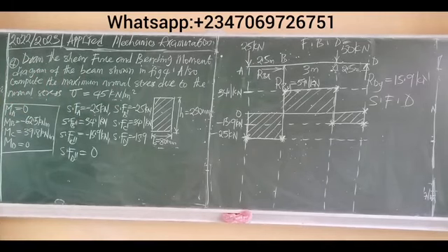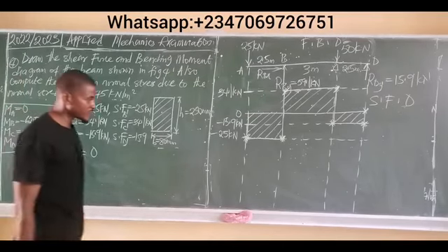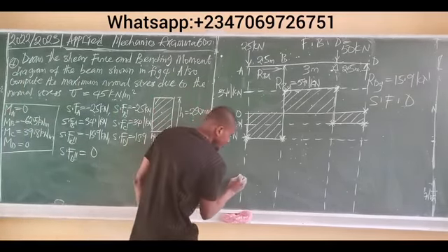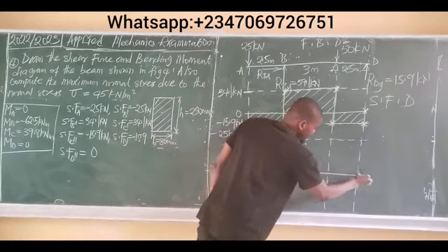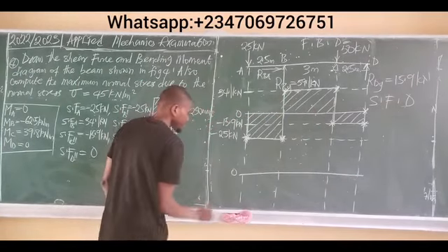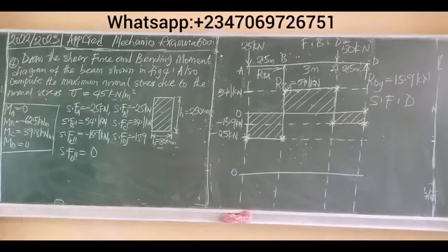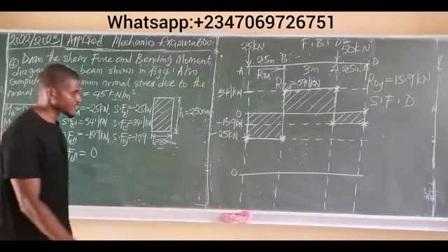So you also look through the bending moment values, picking the highest from the lowest. The highest there is the moment at C, 39.8 kilonewton meters. Lowest is minus 62.5. So we have just two values, one positive and one negative. As usual, you pick out your origin. So let this be the origin, 0. Above the origin are positive values. The only positive value we have here is 39.8, moment at C.